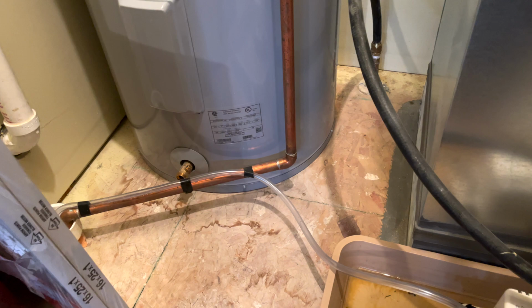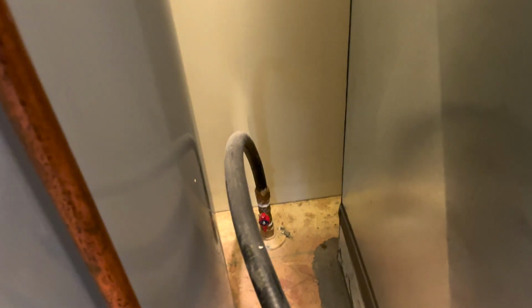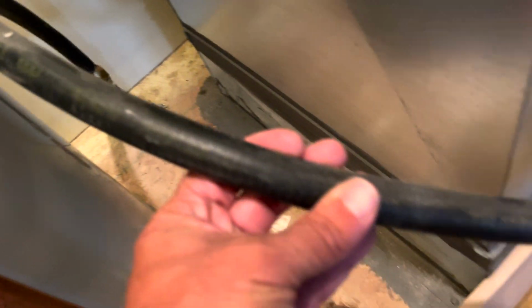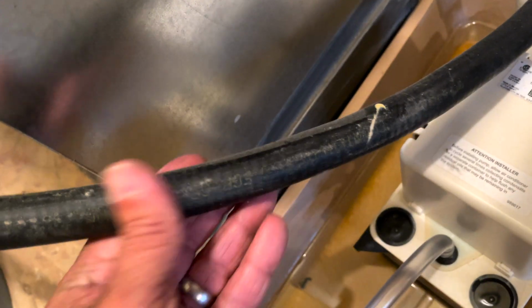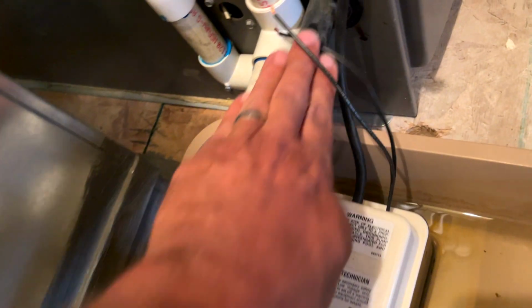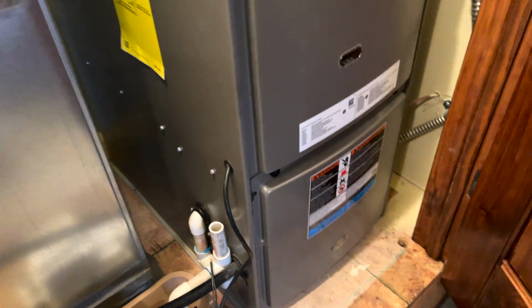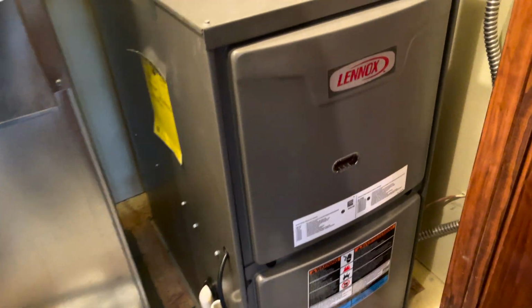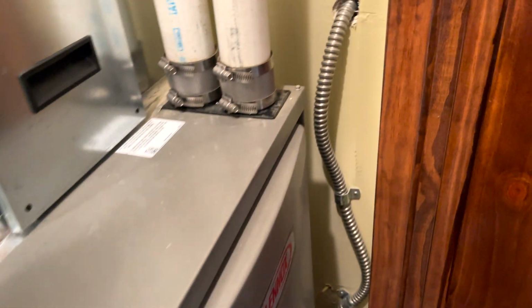Now, the HVAC system is gas fired. We saw a gas meter on the outside, main shutoff valve there, and CSST. This is black, and it's ICC-ES PMG 1052 for underground and slab burial, and the black jacket signifies a protective jacket design. And the black jacketed CSST is referred to as arc resistant CSST. So that's all good. There's the electric supply going to the furnace.